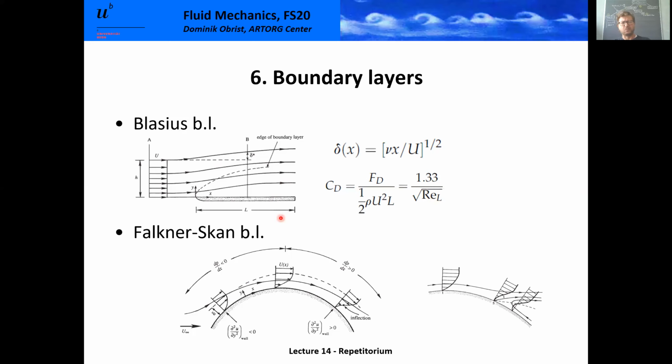Maybe we made at least one extension that we looked at more closely, and it was the Falkner-Skan family of boundary layers, which explain how a boundary layer changes from the upwind side to the downwind side of, let's say, a blunt object, where the flow is accelerated because it has to go around an object on the upwind side, and how it has to decelerate again when the body closes on the downwind side. And this acceleration and deceleration led to a deformed velocity profile.